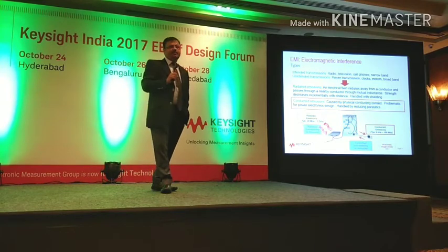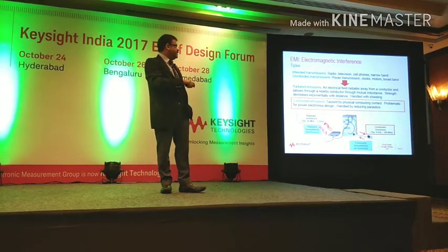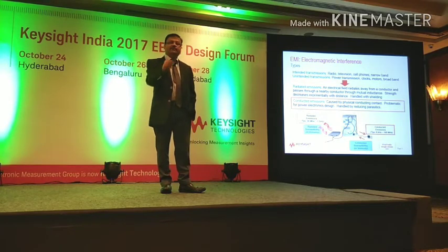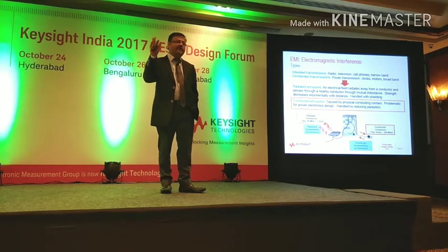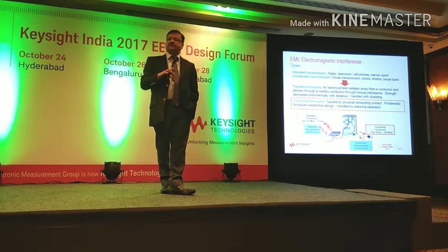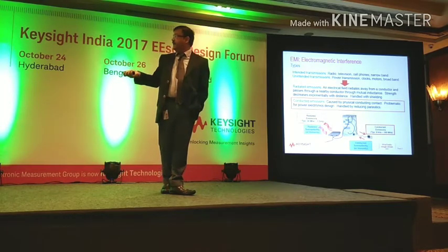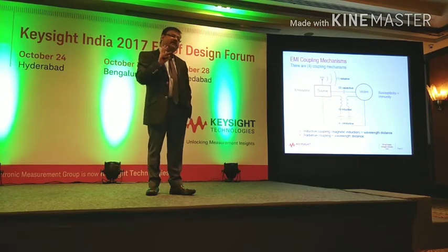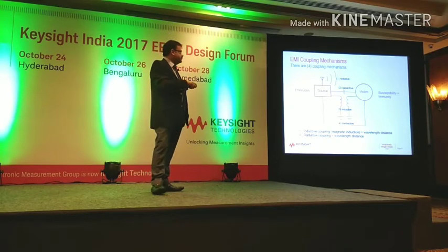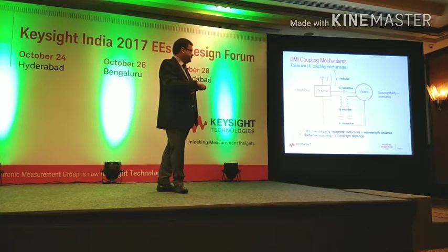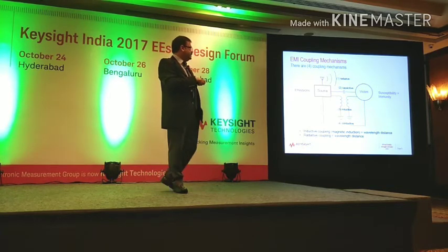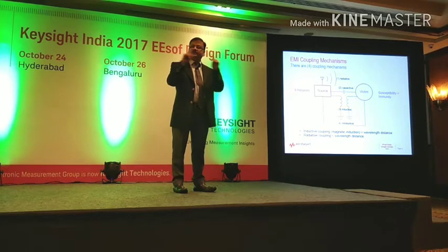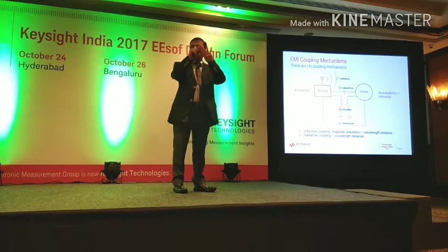Conducted emission is more problematic for them because it's contact-based, physically conducting contact. It's not only you. It can be through wires, through some grounding issue, due to some earthing issue. It can happen from anywhere. So the idea is you have some kind of conducted emission which is happening. Four main coupling mechanisms, of course: radiative, capacitive, inductive, and conductive. So you have a source and you have a victim. That's the whole scene. Between them, these four conditions can exist.